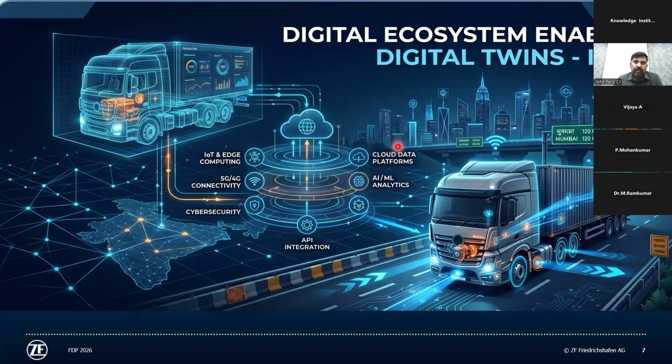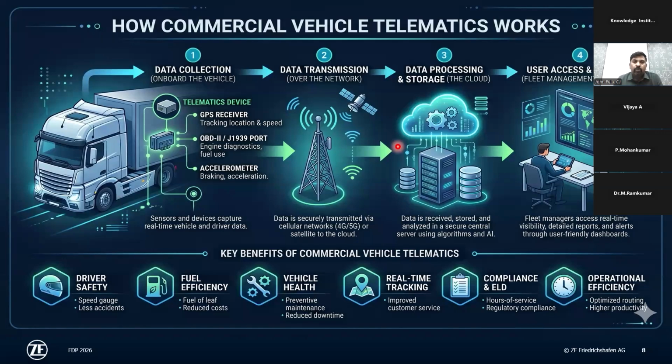For a digital twin setup in the automotive sector, the fundamental is the telematics ecosystem. Telematics is this digital box that sits in the vehicle and logs all data from the vehicle, from different subsystems and different CAN lines, and also captures other conditions like location, environment and driver behavior. Given that data is the key attribute for any digital twin setup, this is the heart of our system.